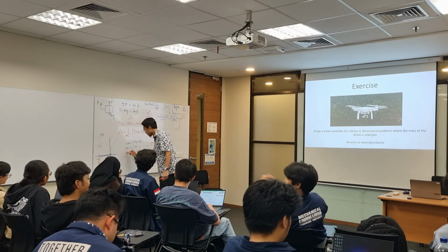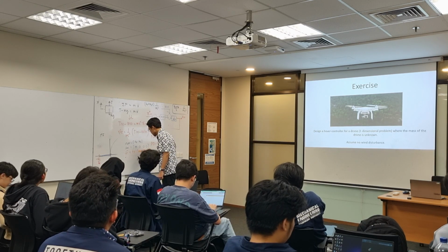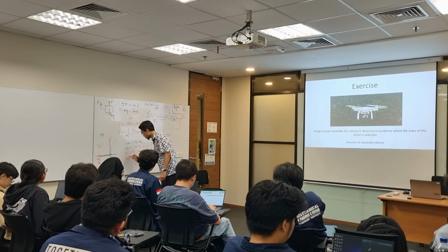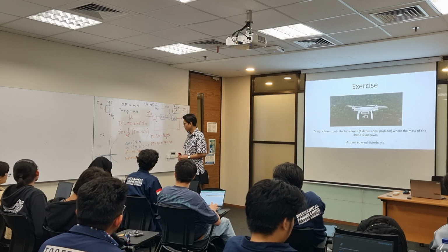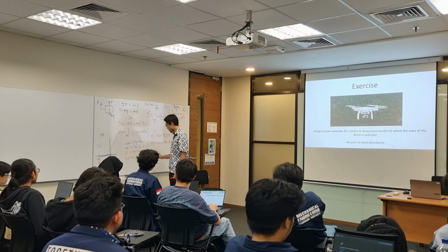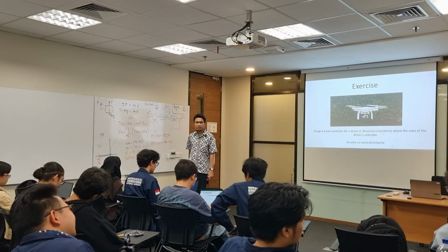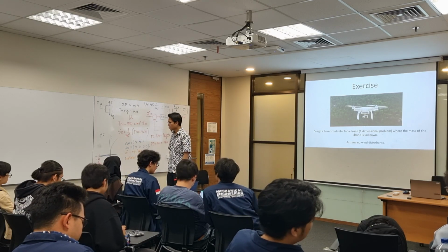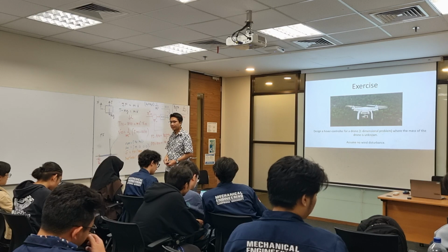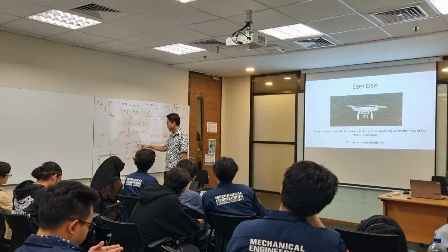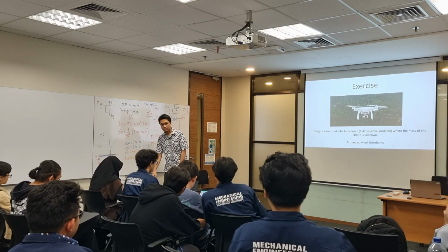Then your G will be TF, and then you write down rlocus G. Let's say M is 10, KP is 5, maybe KI is 1.